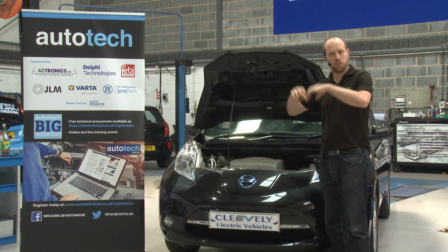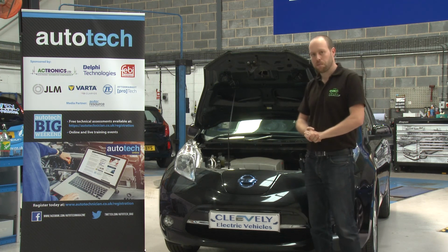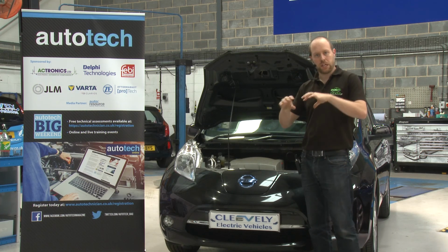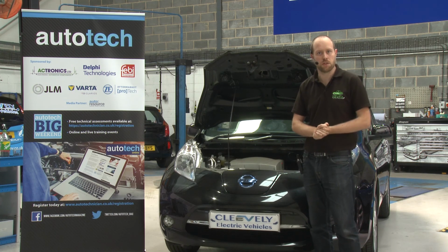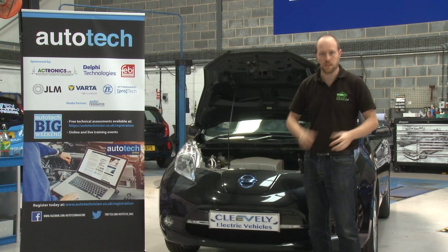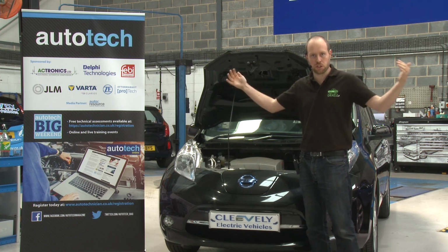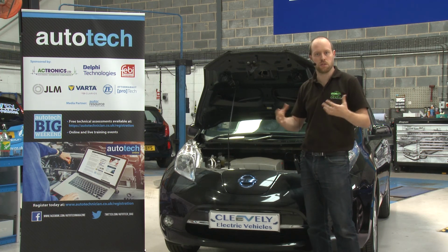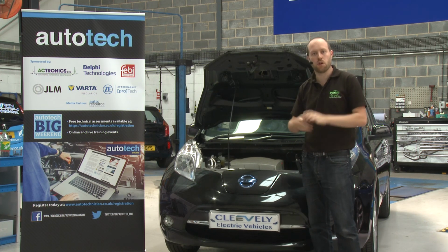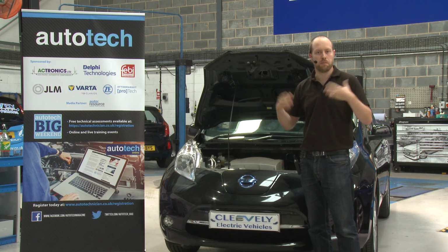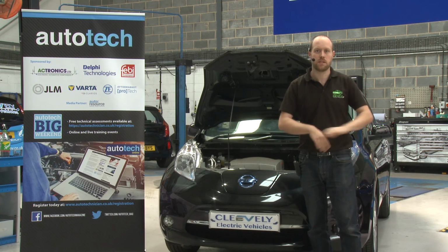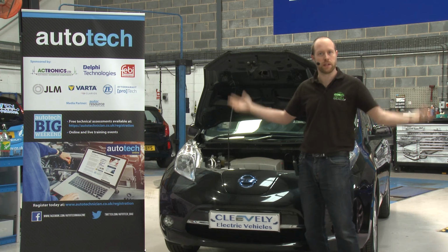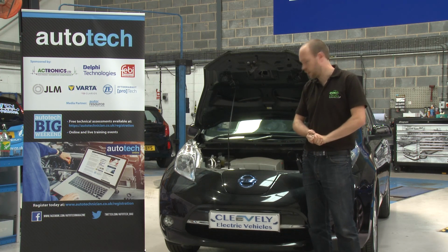are all open by default and you can access the entire circuit, and on some other vehicles, such as this one, the valves are actually closed by default, and if you try and do an air conditioning regas, you'll find that you need to connect diagnostic equipment and tell the vehicle that you're doing a regas. All the valves will then be put to the optimum position to let the whole system be joined together so that you can do the regas. And if it's got a complex coolant circuit like this, you put it into bleeding mode, and again it will put all the valves in a suitable position, especially when you only have one header tank like this, in order to fill the whole circuit. It will run the pumps as well in order to circulate the coolant, in order to make sure those cooling systems are properly bled.